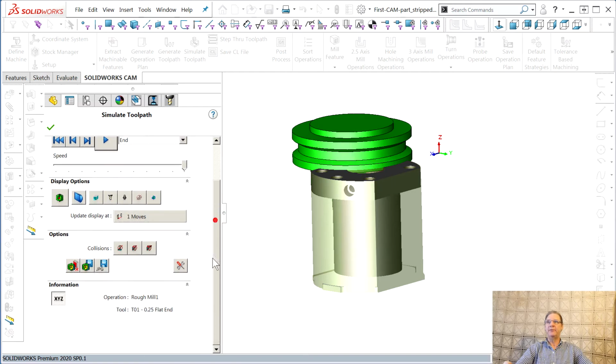You've just got yourself a $15,000 spindle and probably a job if you work for other people. This is because by default, it sets tool ignore collision, tool shank ignore collision, tool holder ignore collision. And what you're allowed to do is you say, oh, cut it. If it goes there, take that material away so that when you do this thing and check the part to see that it's made the way you want, there's all this missing stuff. Or you can pause on collision.